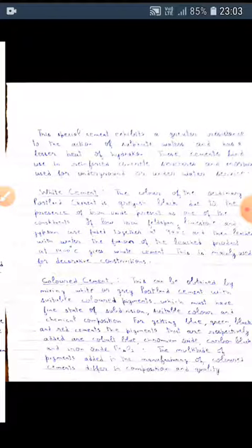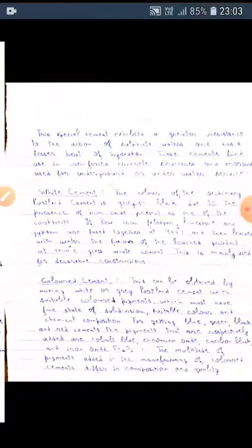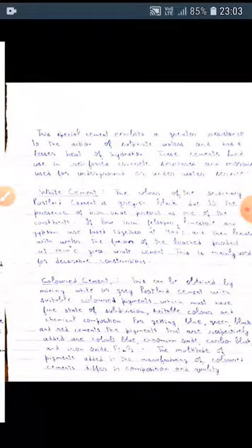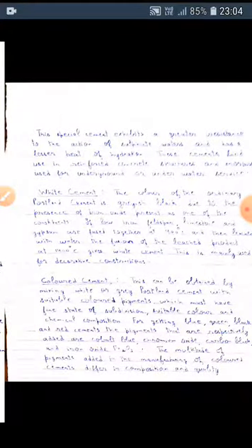Construction makes wide use of cements of different colors and hues. They are used in the fabrication of mineral paints, mortars, and concretes of different strength and resistance to frost. According to strength, colored cements are available in three brands: 300, 400, and 500 kg per square centimeter.